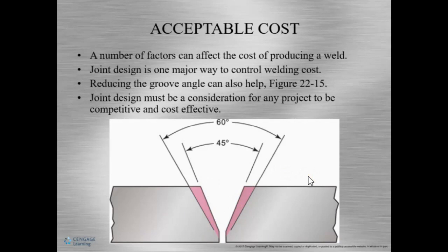in preparing the joint. But incorrect joint design or a selection of the process can cause issues with accessibility to weld the joint, meaning if we have something that is too tight in here for the process that I'm using, it might not even be worth the savings that we had.